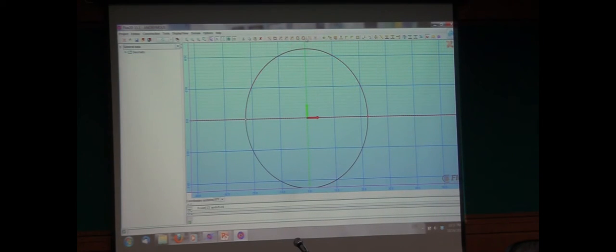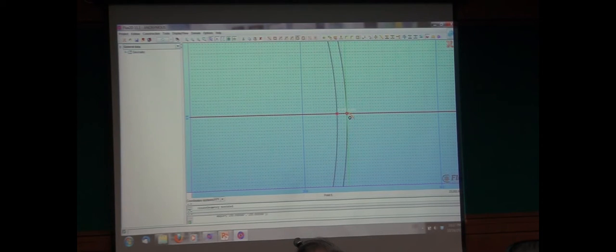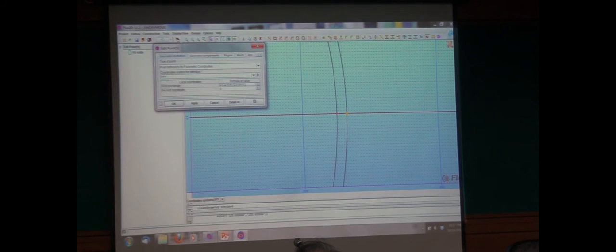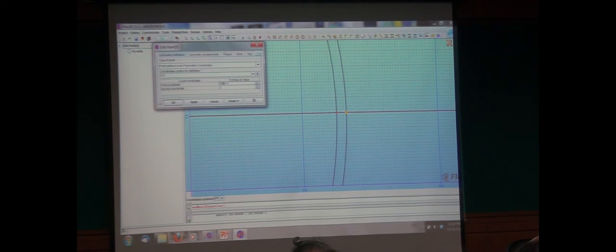So let's enter another circle. That's going to be for the other side of the air gap. So I'll just do it to a value which is big enough, because otherwise we're not going to be able to see. So I'll go here for now. And again here, if I wanted, I could actually enter something here. Sorry, escape. So it could be ORR plus the gap, and I can say, for example, plus 1 millimeters. Yeah, why not? I can do this. Okay, just to show that even though I'm using a sketcher, I can still enter very precise information.